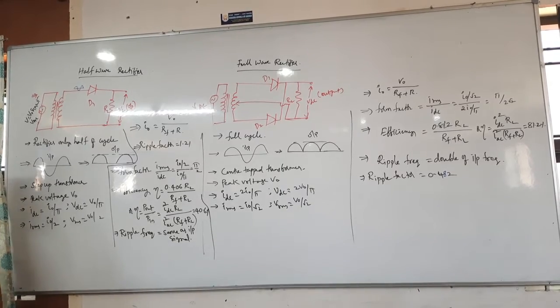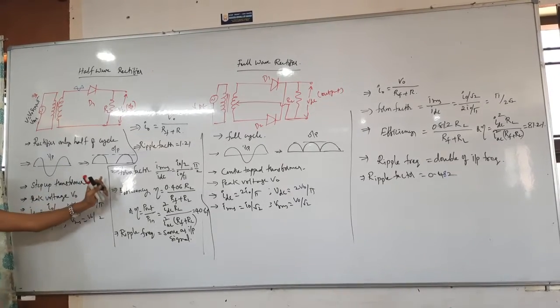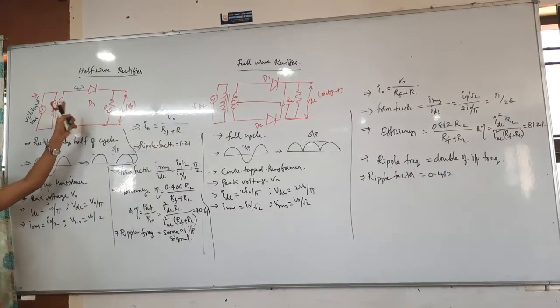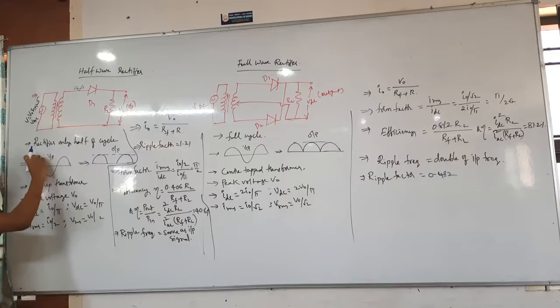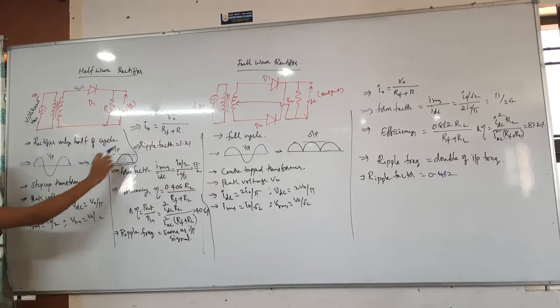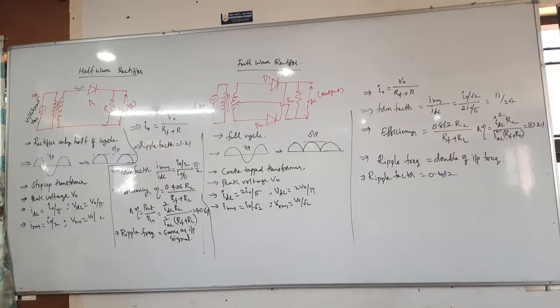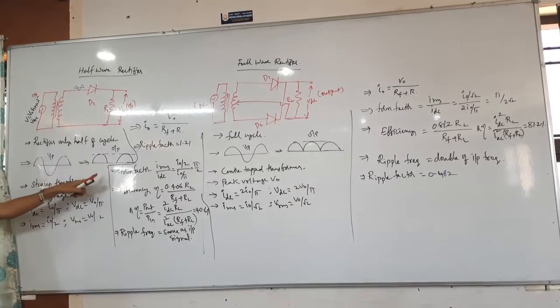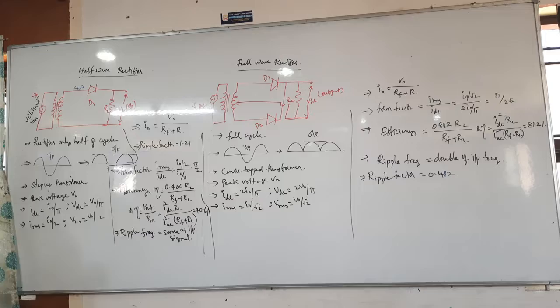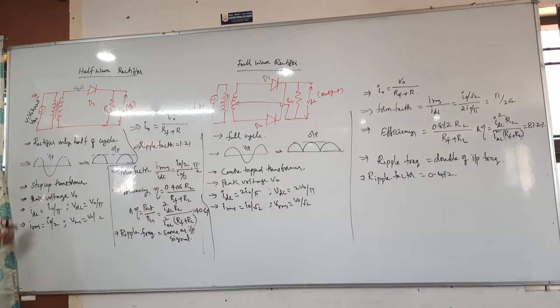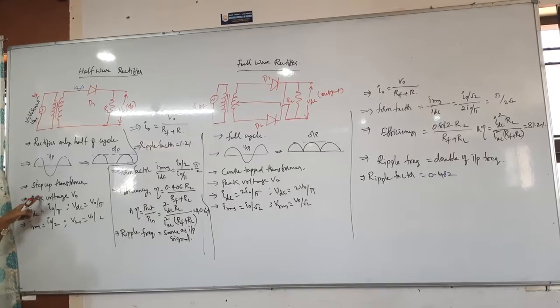So whenever you compare the input and output signals here, the diode is in forward bias only, so it is taking only the positive half input and giving the positive half output here. Clear? That is about the input and output diagrams. Here the negative half is not passed; it is filtered whenever the diode is in reverse bias. Next, the transformer used here is a step up transformer.